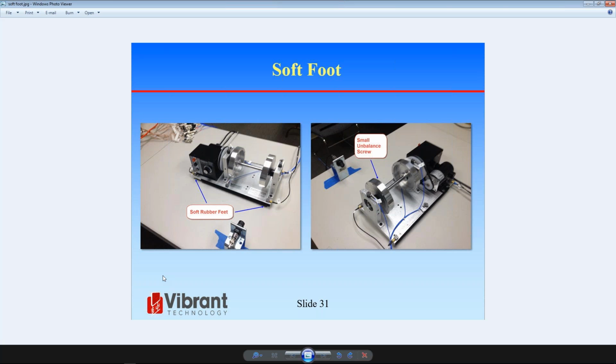So we simply varied the speed of the machine, and Emiscope, using the tach signal, can measure the machine speed. It just finds the biggest peak in the tach signal spectrum, and that's the speed of the machine. And this machine's sitting on some rubber mounts, so as we change the speed of the machine, the ODS measured with these accelerometers is going to change.